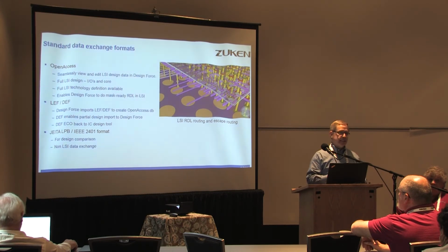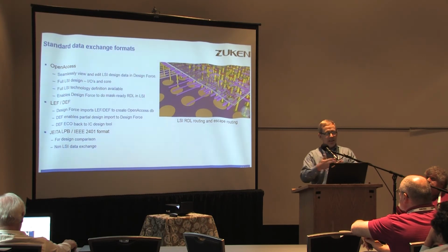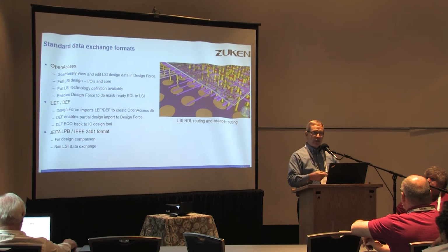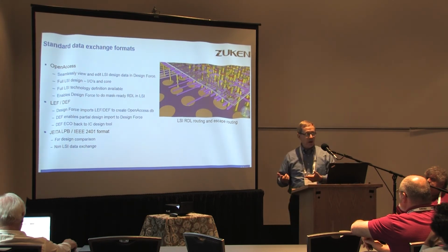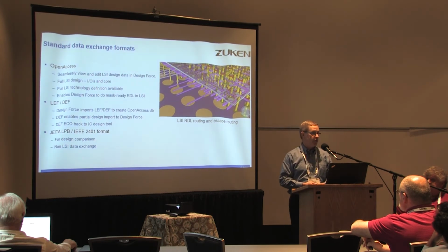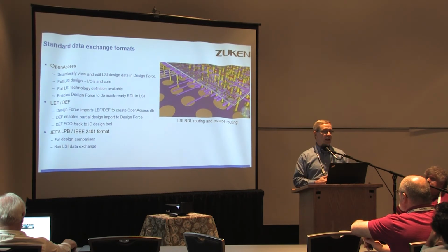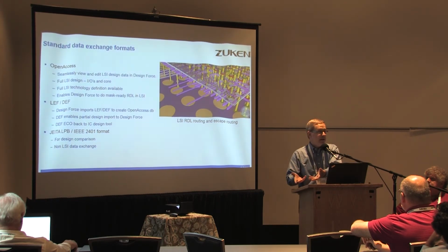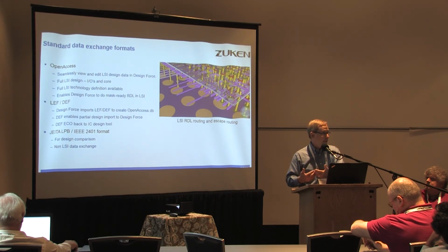Another important aspect is ECO back to the IC tool. We don't have a full IC design tool, so we do OpenAccess down to the I/O drivers. Now when we make changes in Design Force on the pad ring, the bumps, and RDL, we need to pass them back to the IC design tool, which is owned by one of the other EDA vendors. So we typically will either give the OpenAccess database back, and they can use it as is and build from that.